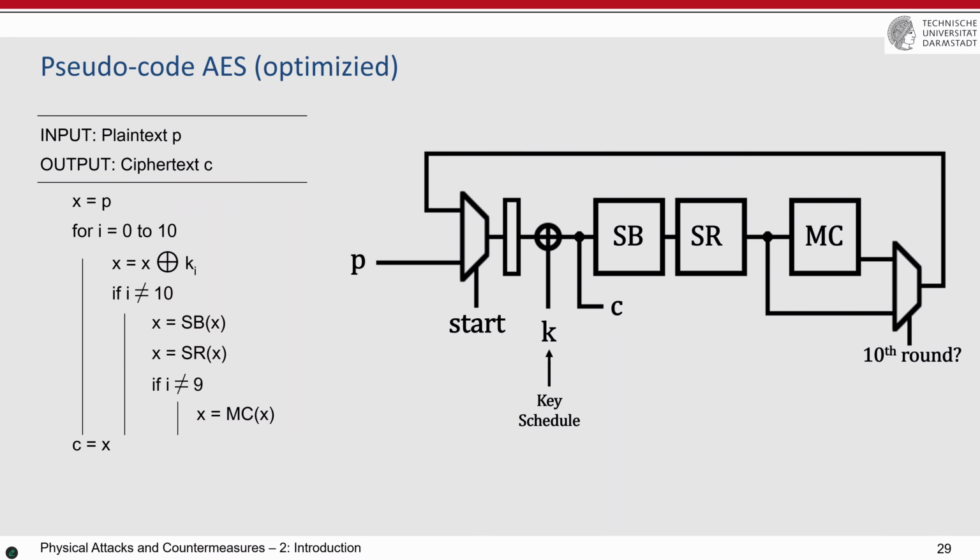Then what you can do, this is exactly the same thing. I put a register here, the loop as before. The only difference is that there are not 2 XORs. If you remember, there was 1 XOR here and 1 XOR here. The XOR came to the loop here, and then you do it just once. You can also put the register not only here, you can also put it here, or here, or here, or inside this loop, anywhere that you want, or multiple registers.